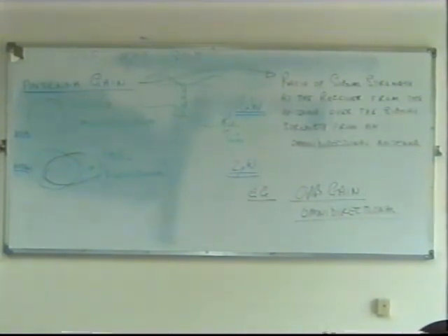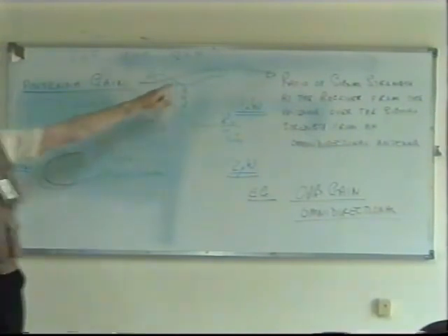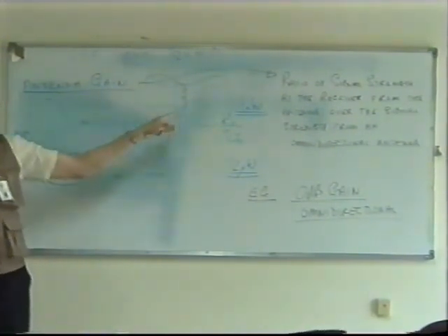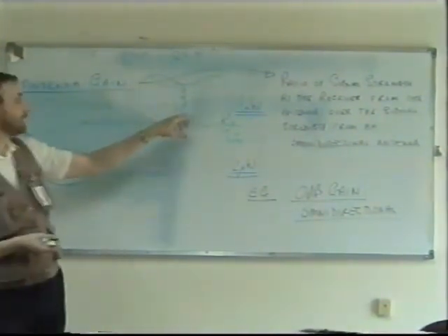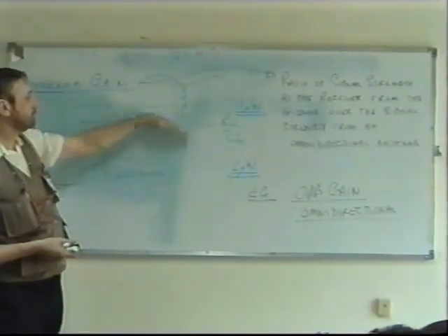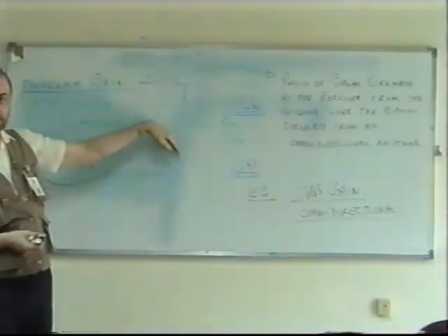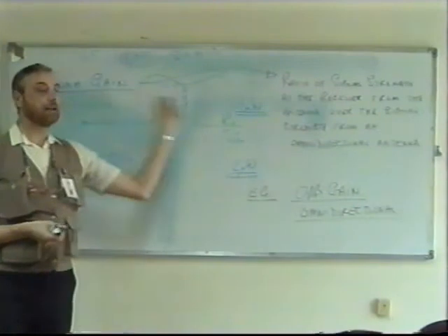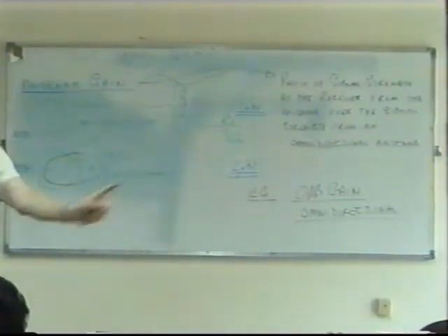You'll see some antennas rated at 3 dB. Probably it could be a stacked array or collinear. I mentioned that both words could be used. Basically, they do cut out the top and bottom powers, but they can still be omnidirectional around the antenna. So they could still work for mobile. What's the other name? Collinear.